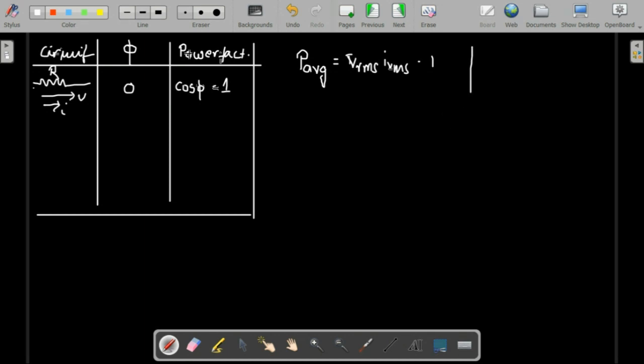That's quite obvious, because when we talk about power, we know it is nothing but I square R. So if this I is the current, R has to be maximum. If you are considering an AC circuit, it is actually I square Z. So whenever Z is maximum, okay, you're going to get that maximum power, right? So you can see here, this is my maximum power that is possible.